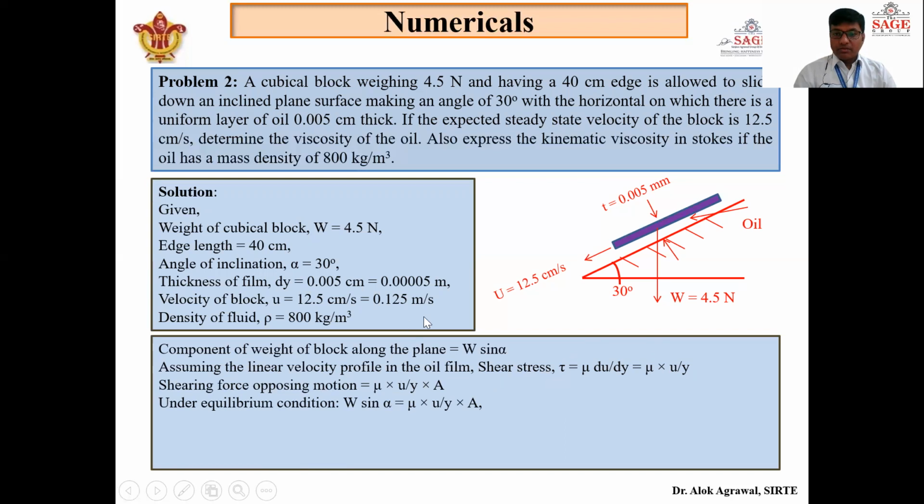Under equilibrium, means the block is not accelerated, it is moving with a uniform velocity. It is given that it is a steady state velocity, meaning the velocity will remain constant and will not change with time. So if the velocity does not change with time, we can consider that the block is in equilibrium, and the force acting in the direction of motion of the block will be equal to the shear force, that is given by mu into u by y into A.